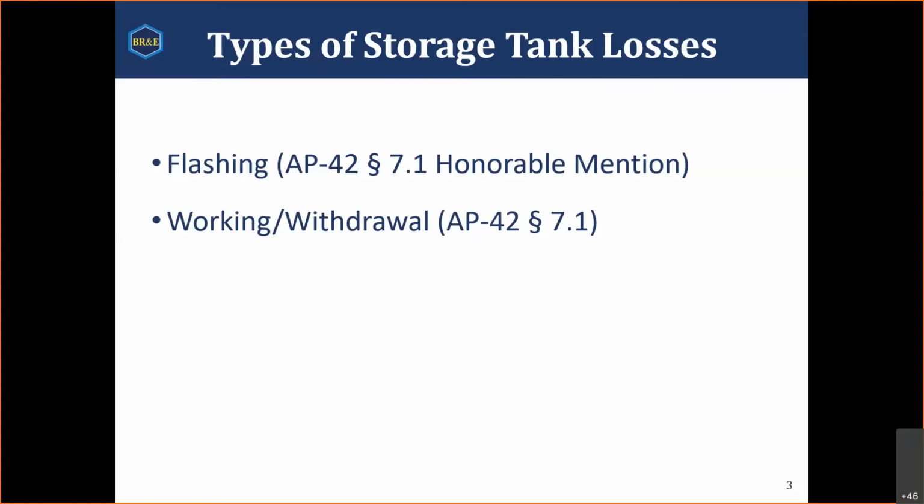Withdrawal losses are for floating roof tanks, and basically as liquid is pumped out of the tank, some of the liquid clings to the sides of the tank and to fittings inside of that tank and evaporates, and that's what we call withdrawal losses.